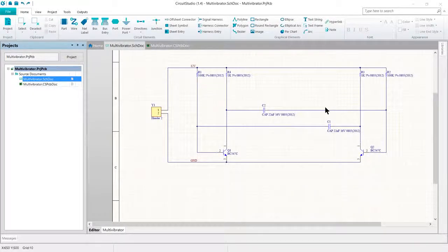Before we pass our captured design into the PCB for layout, we want to prepare the PCB by defining the board extents. Before we begin component placement, we want to define and modify document options and design rules and define the layer stack we plan to use. So first, let's go ahead and get our board shape defined.